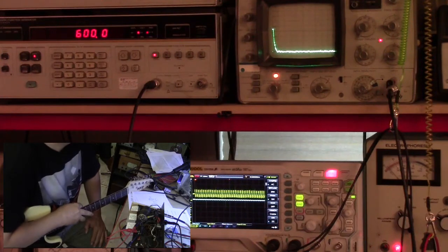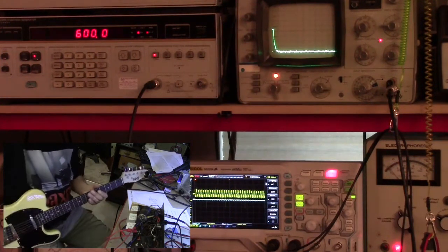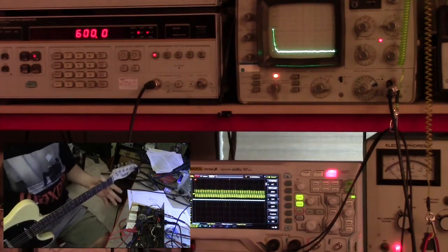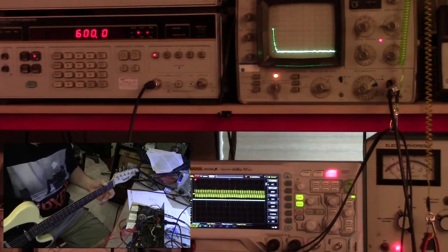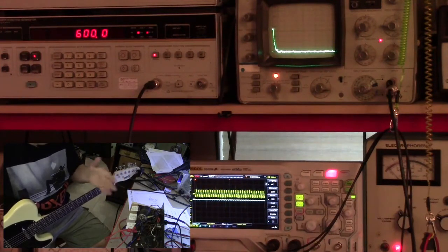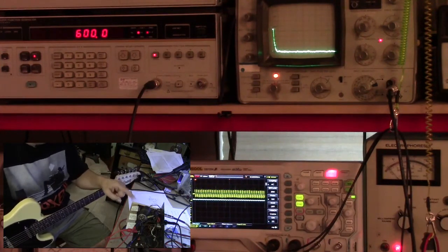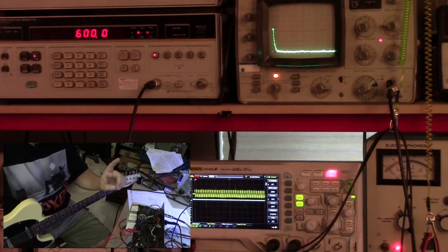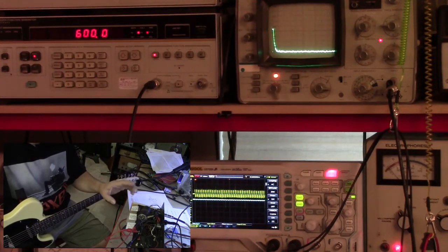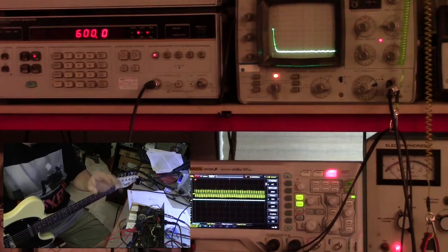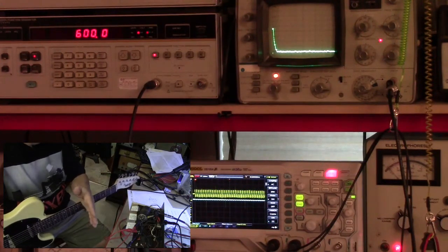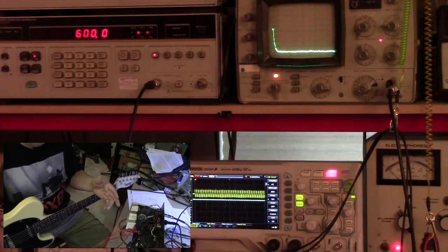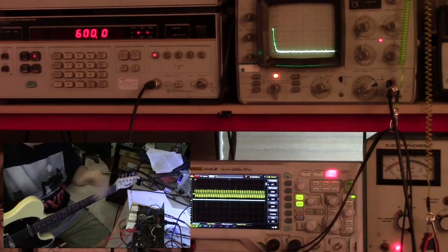That's a light touch, and that is 200 millivolts. So this guy puts out between 100 millivolts and almost a volt. So either guitar could clearly drive this pentode up into the hundreds of volts, which is what's going to get fed into the potentiometer, so we can change the voltage level going into the output tube, which is a 6F6. But we have plenty of drive signal, and this has plenty of gain.